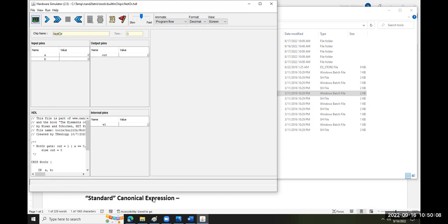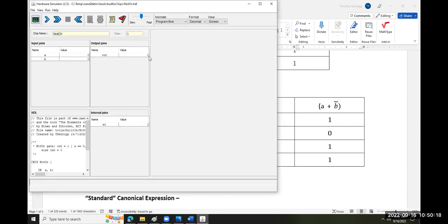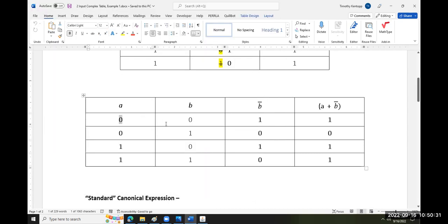Yeah, we see it. So what's the case we're testing for? The one case that's false. It's going to be when A is false and B is true. I should be getting a false. Everybody see that? Because it's already giving me the first case. The value is 0, the value is 0, and the output is 1. I've already done this first case. The input is 0 before it's flipped with a not. That's 1. I already have one case resolved.